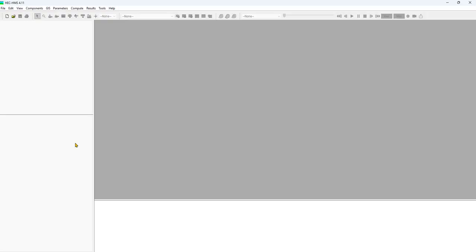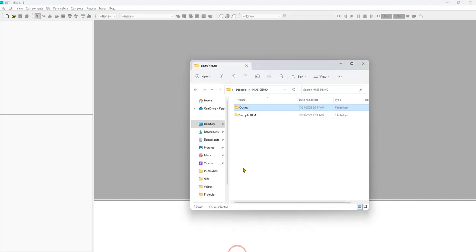In this video, I'm going to show you how to set up your HEC-HMS model from scratch, delineate your watershed, figure out your subbasin, characterize all the parameters in your subbasin, and eventually do a simple hydrologic modeling for different watersheds and different subbasins. But before that, I'm going to show you the data that I have.